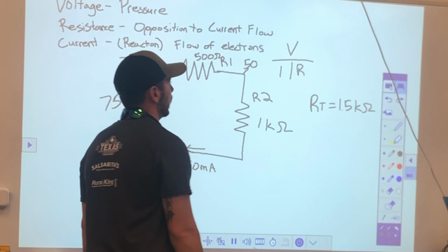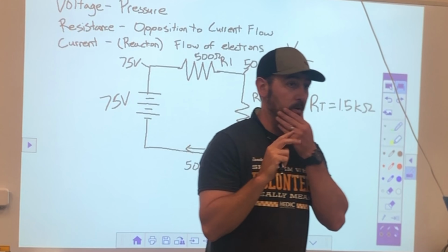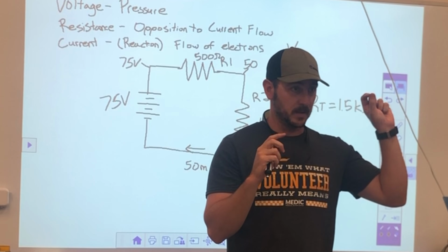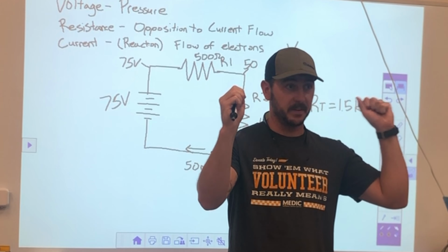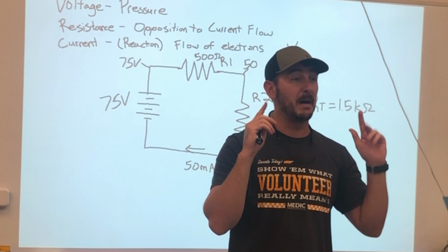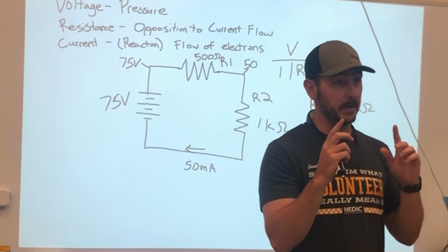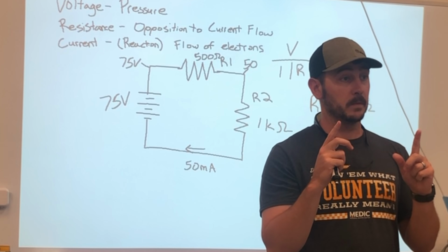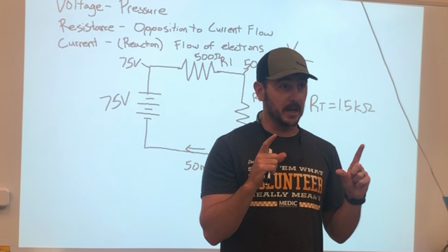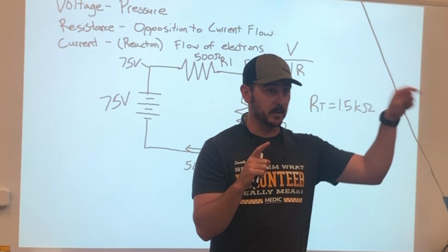Now, think of a multimeter, and we haven't been through meters yet, but remember, voltage is just a difference of potential. I've got a potential here, I've got a potential here. The difference is the voltage amount. That's how my meter reads. Your meter has got two leads on it, right? The black and the red. When it's set on volts, all it does is say, how much voltage do I got here?